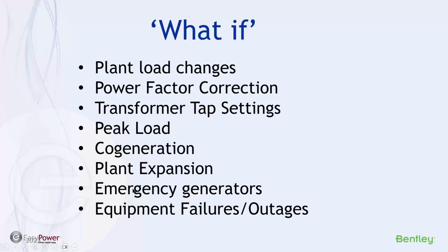And then the impact of firing off emergency generators with certain systems online. So anyway, PowerFlow is extremely useful in debugging my one line and making it more accurate. And then in operational, it gives us the ability to do some troubleshooting and what if scenarios as we're trying to improve the capabilities of our system.